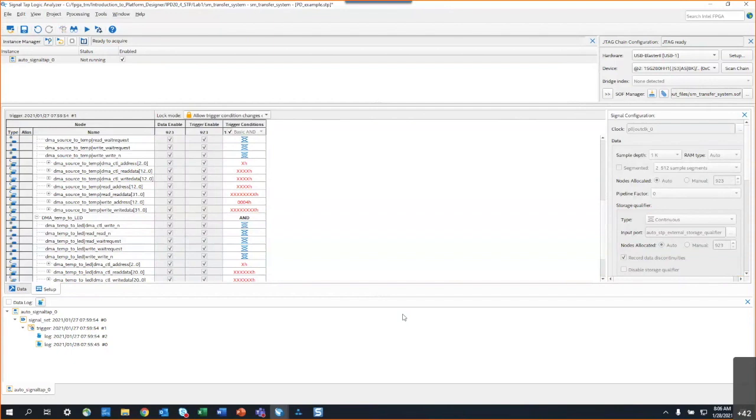Also, when I read the FIFO data out compared to the FIFO data in that was saved, they are different sometimes. So what could be causing this? And would you recommend using a different clock for the SignalTap sampling, such as 250 megahertz, to sample the ADC data that is clocked in at 125 megahertz?